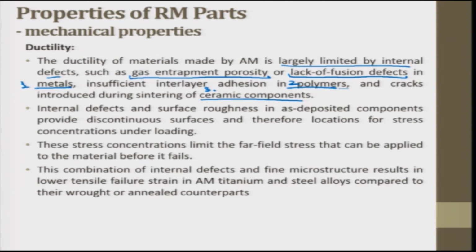In metals, it is gas entrapment porosity or lack of fusion defects. In polymers, it is insufficient interlayer adhesion and cracks in ceramic components. These determine the ductility.